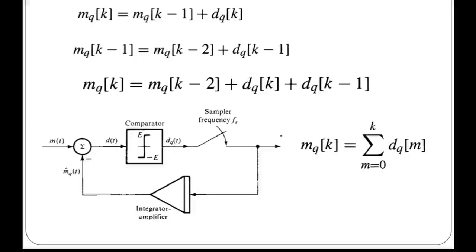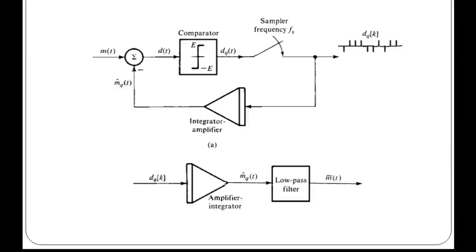So what is the reason to use delta modulation? We have observed in the PCM that it transmits all the bits which are used to code a sample. Hence the signaling rate and the transmission channel bandwidth are quite large in the PCM. To overcome this problem, delta modulation is used. The question is how it will work. What is the working principle behind delta modulation?